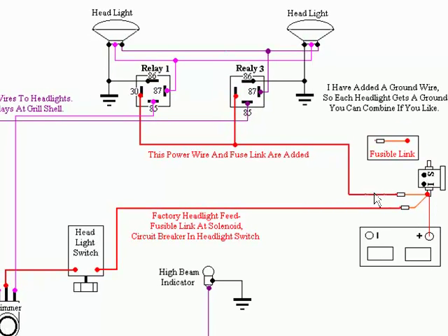In any case, here goes the current, and then it goes in here and in here. Now, of course, it has to be connected. Well, that's where the dimmer comes in. So this one here is the low beam, and this one is the high beam. That's just where the current comes in. And this is the headlight switch, which then tells the dimmer which mode to be in.